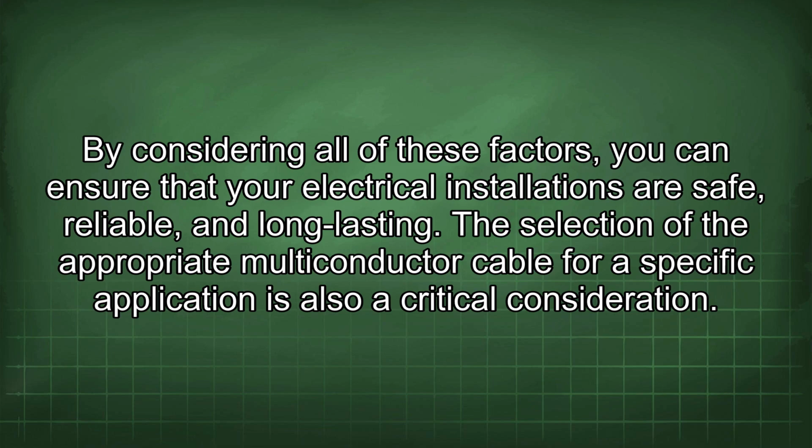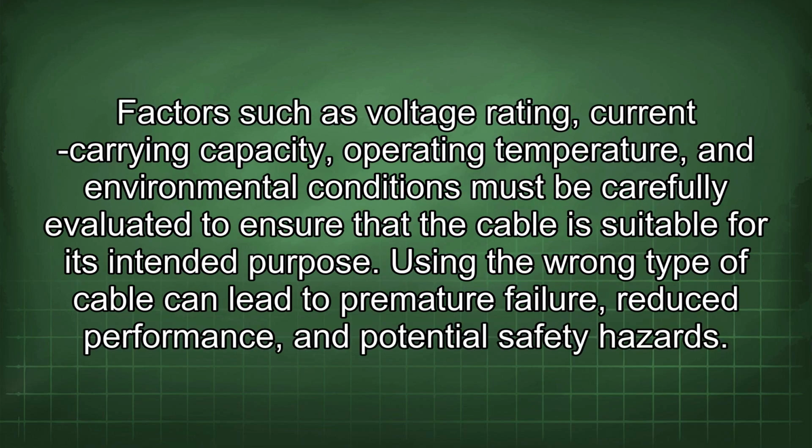The selection of the appropriate multiconductor cable for a specific application is also a critical consideration. Factors such as voltage rating, current carrying capacity, operating temperature, and environmental conditions must be carefully evaluated to ensure that the cable is suitable for its intended purpose. Using the wrong type of cable can lead to premature failure, reduced performance, and potential safety hazards.